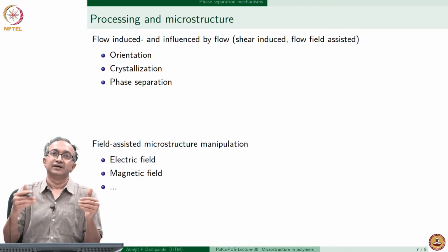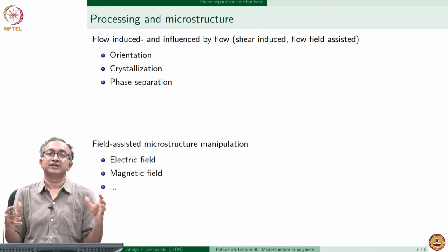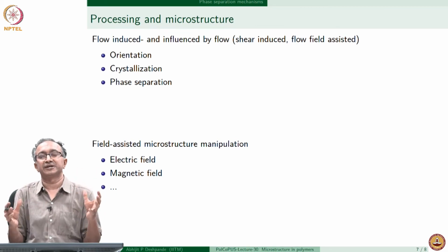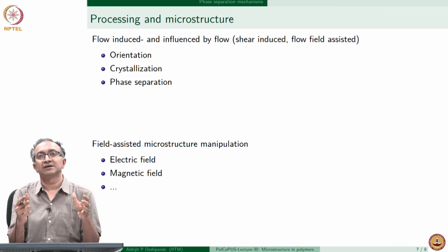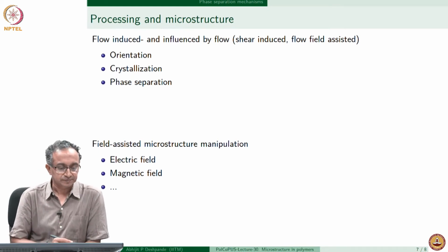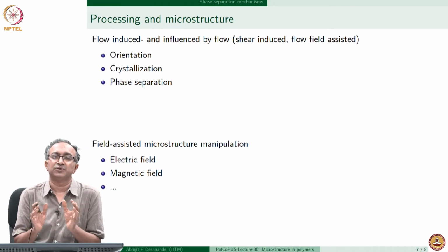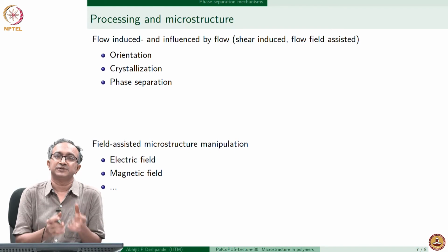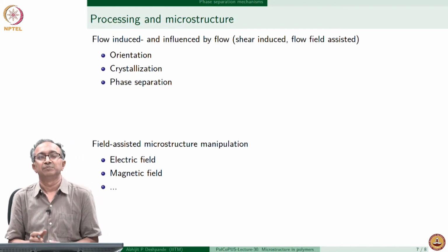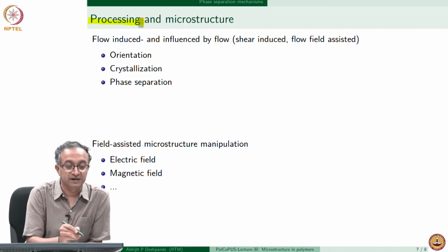Because there is an unstable phase separation formation, there is co-continuously everywhere an A-rich region and an A-lean region, or polymer crystals will be spread throughout. It's observed only in lab conditions or for very few specific systems. So one of the things we have to be very cautious about is how the processing being done on a polymeric system affects its microstructure. Because in the final part, it's the microstructure which is very important, but the processing will have a large influence on it.